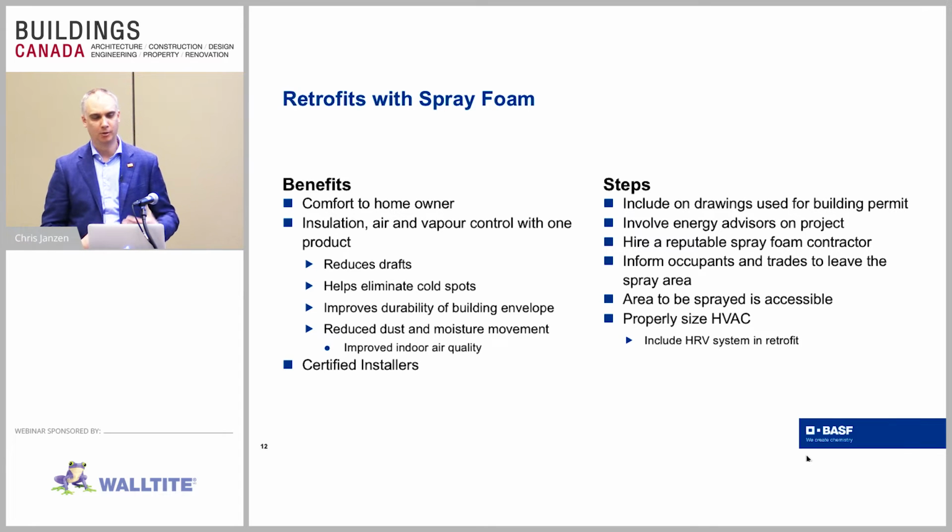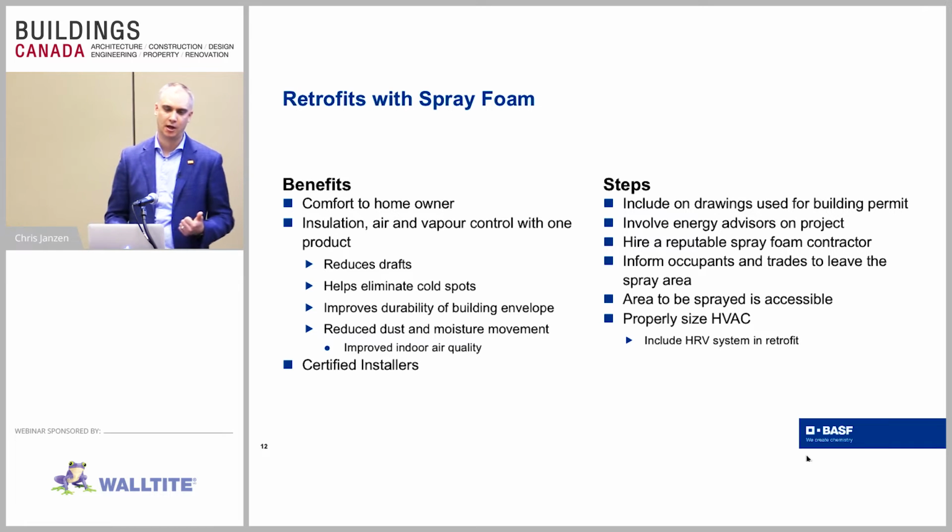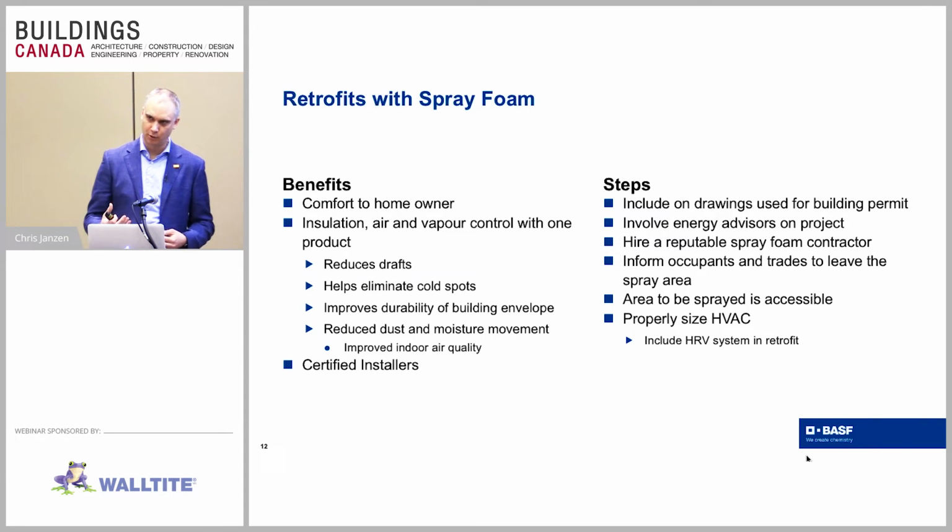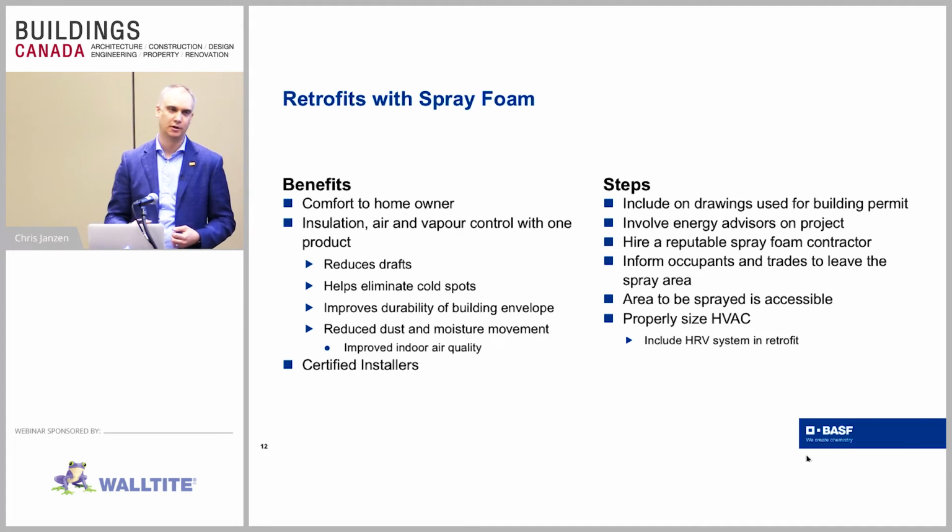that you want to convey to the client is spray foam provides comfort to the homeowner, environmental comfort. When they're in the room, it's a more comfortable room to be in. It's a hard thing to quantify, but it is more comfortable. And the reason for that is because you're getting your insulation, your air and vapor control with one product. What that does is, because it's reducing the drafts in the room, now you don't have cold spots, and it also improves the durability of the building envelope because of the air sealing properties of the foam. Now you're not going to have to worry about moisture or dust coming in from outside, no air leakage carrying moisture or dust onto the inside. So you don't have to worry about mold or any kind of environmental contaminants from the outside of the building getting inside, affecting the indoor air quality.